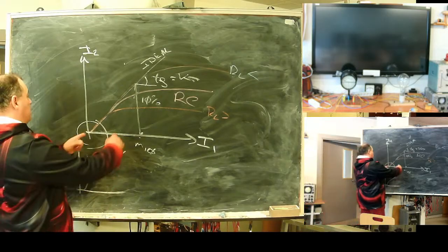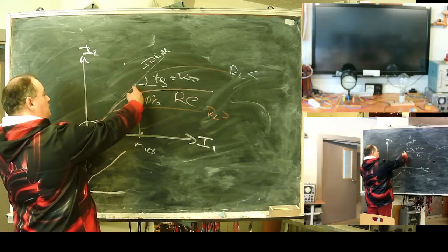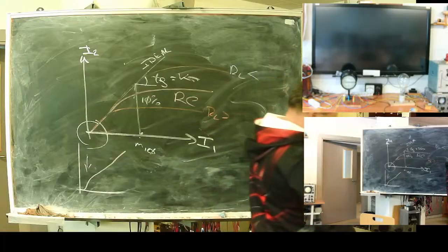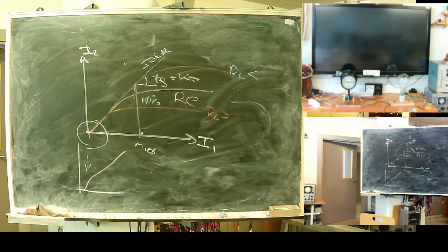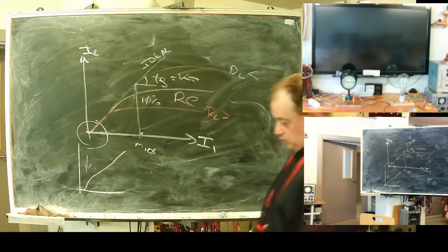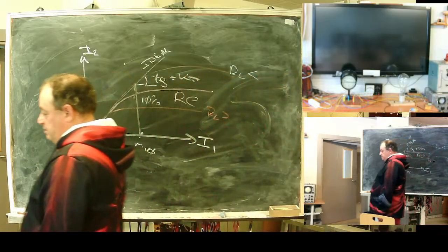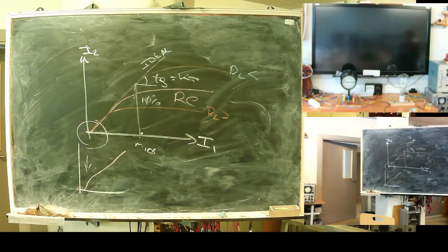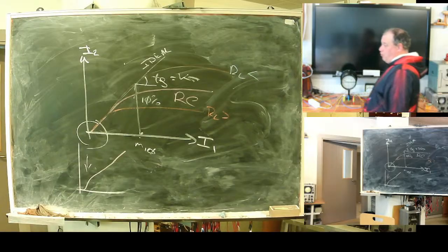So, to achieve precision in this area, you should find a balance between the burden you put on your current transformer and the amount of money you're ready to spend for a core.